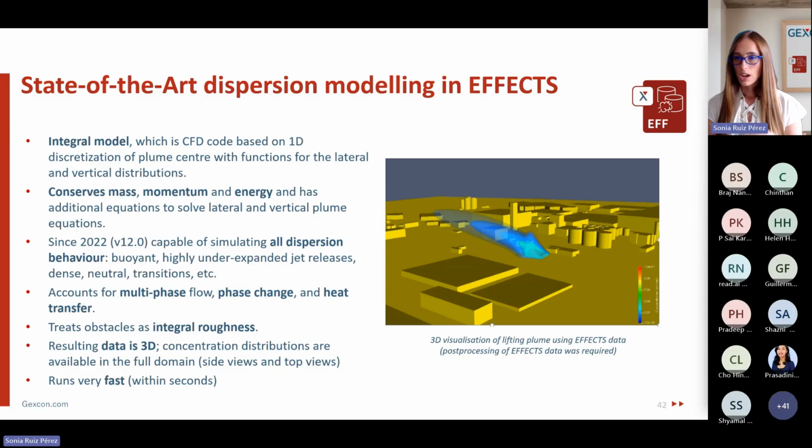In these initiatives, a release of carbon dioxide behaves a little bit differently than other chemicals because it suffers from this solid-vapor equilibrium. And therefore, if we have a CO2 jet, it will flash out as a vapor cloud of CO2 with solid snow particles in there.